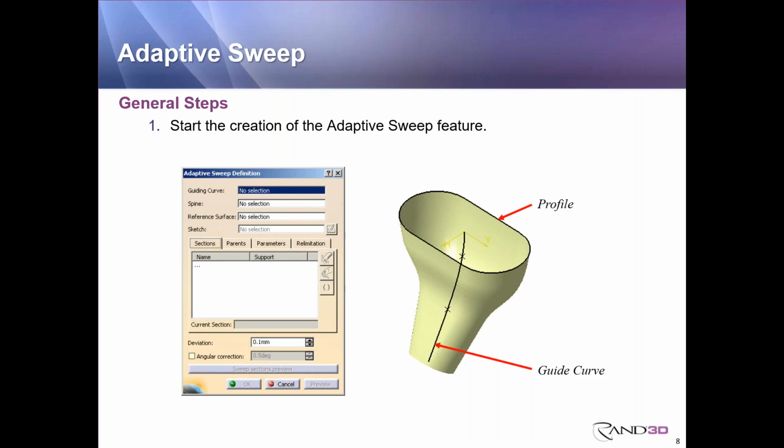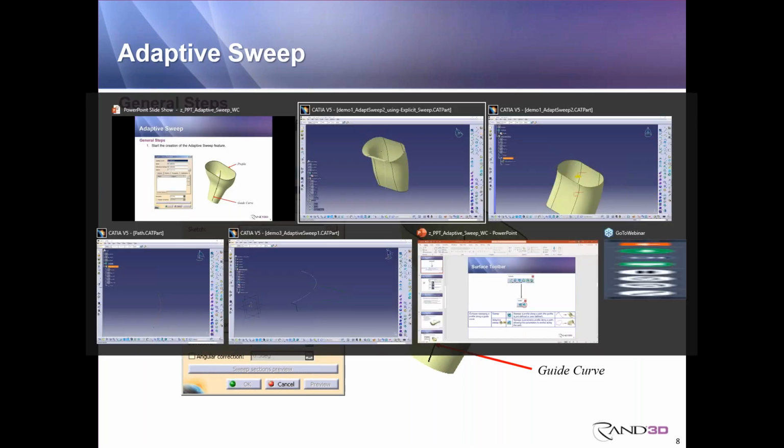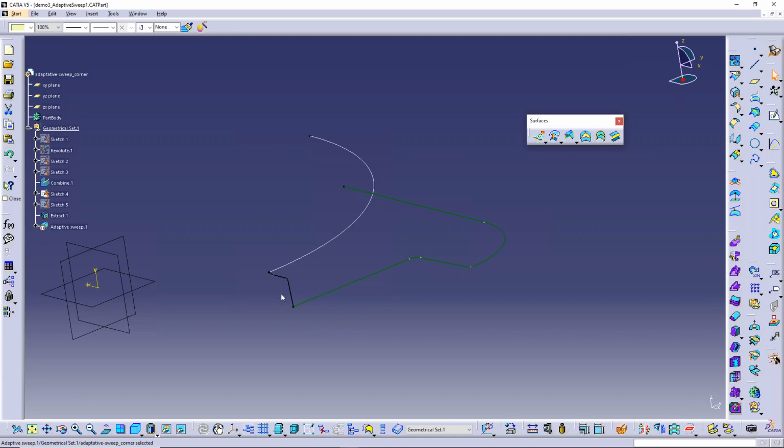You can create a reference surface on the fly if you wanted to. You can right click in that field there and go through the process of defining a reference surface. You can pick even one of the planes, like the XY plane from the model as a reference if you get that to do what you need. If you have a mean plane definition, for example, that does what you need.